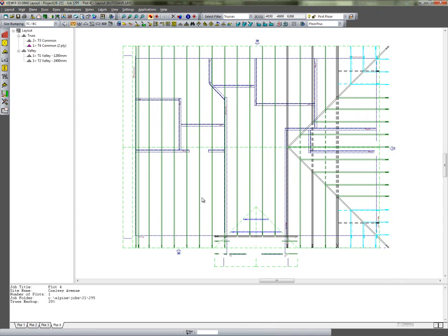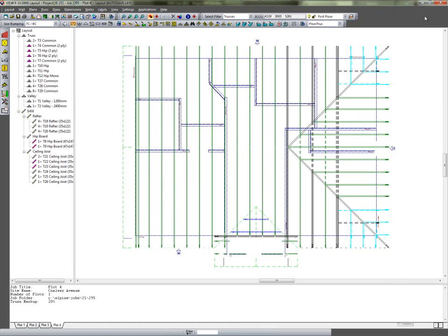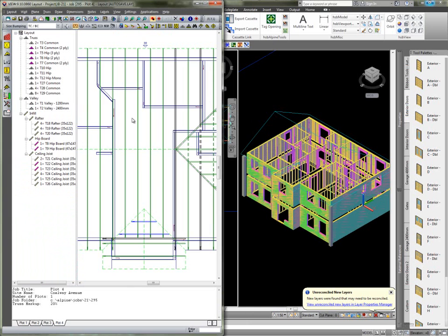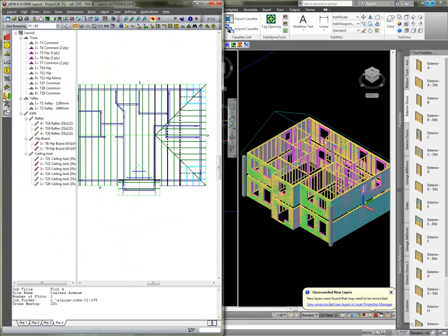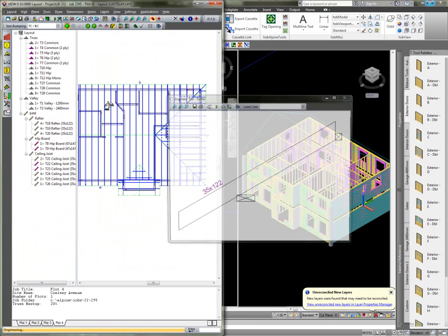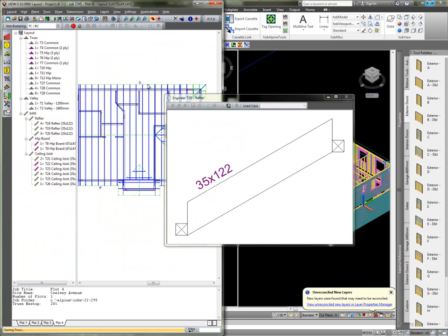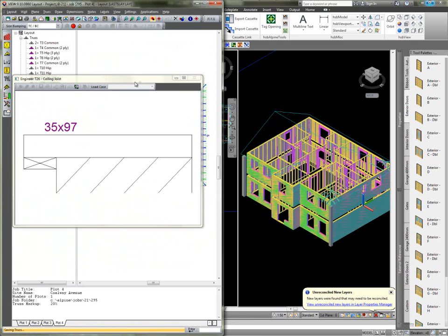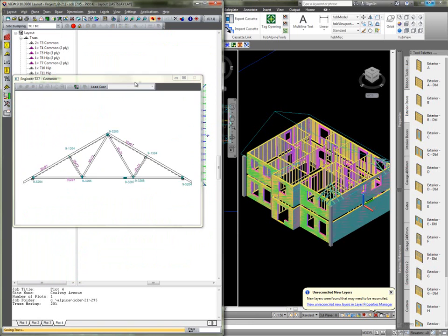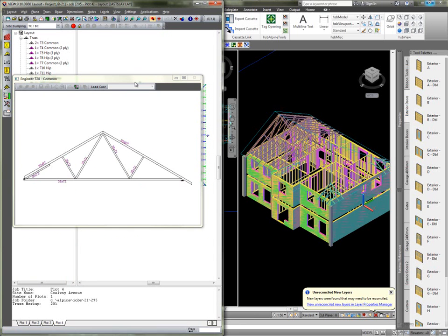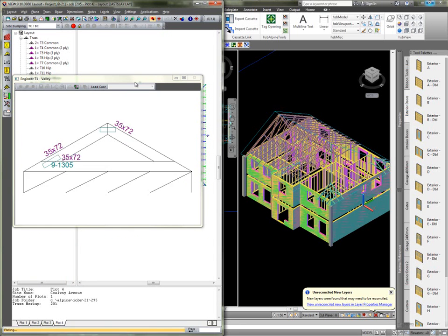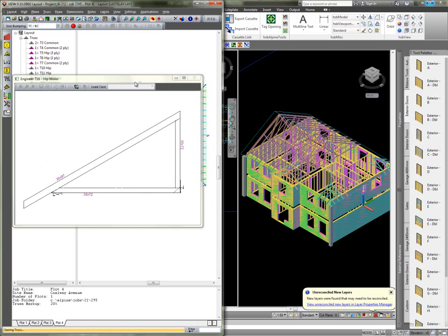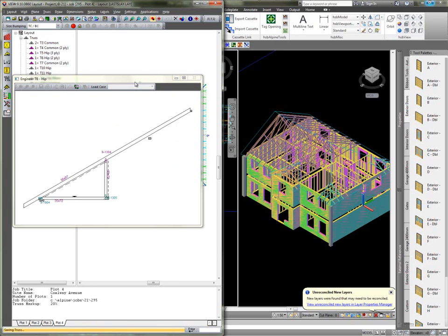Based upon the criteria and the values that you have entered, it automatically lays out your trusses and all loose info. Now that we've got all of this laid out, we will begin the engineering process. What's important to notice here is that as we are engineering our model, all of this engineered information is automatically appearing within the hsbCAD or timber frame design model.